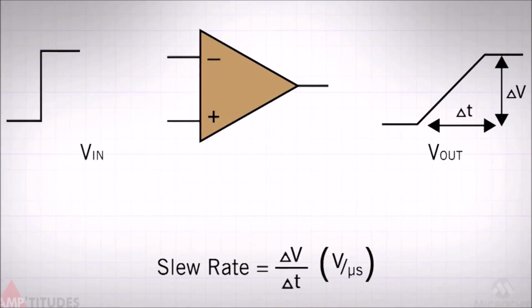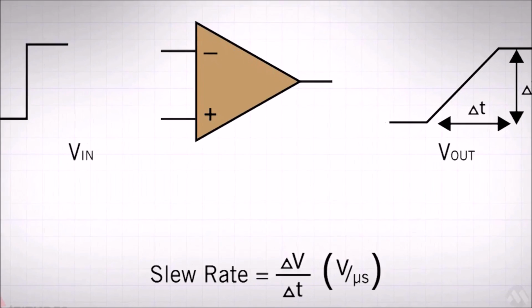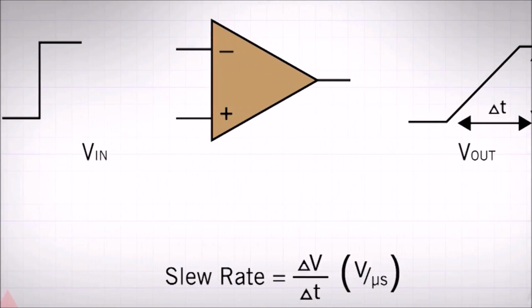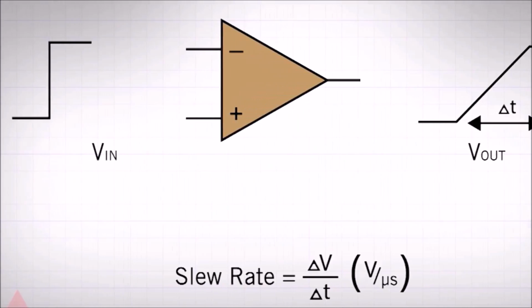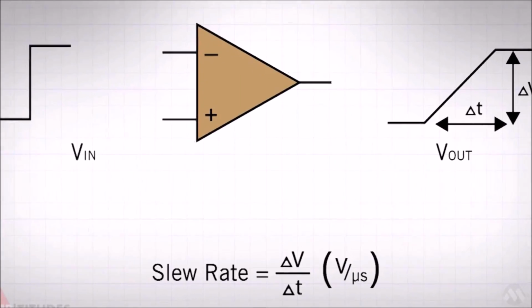So this was all about slew rate, and the next time you need to select an amplifier and you are concerned about the speed, you must consider the slew rate of that amplifier.